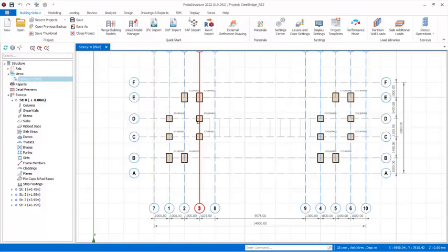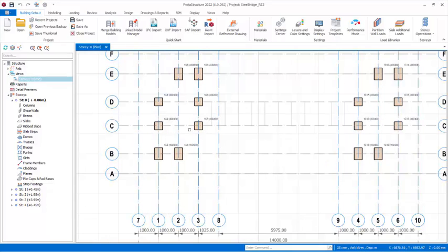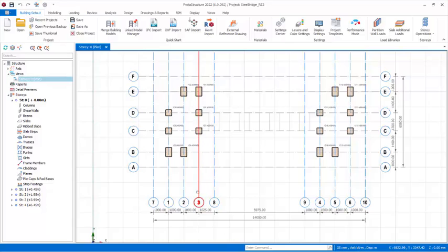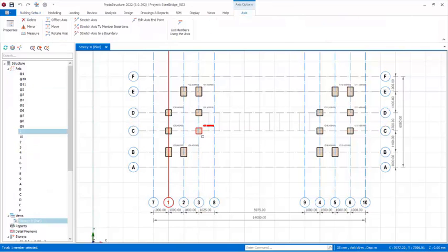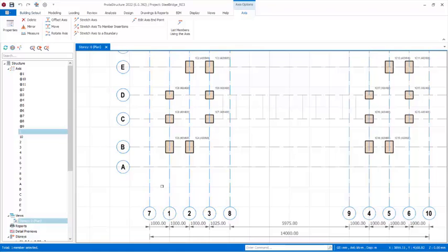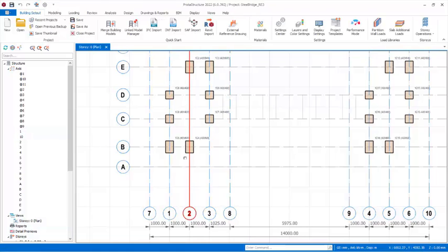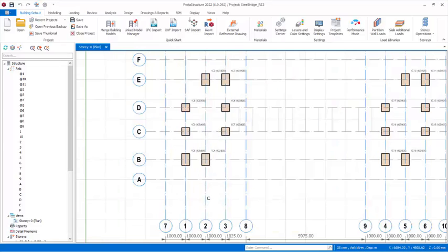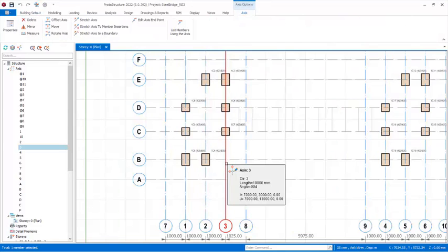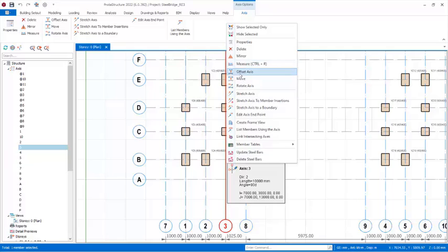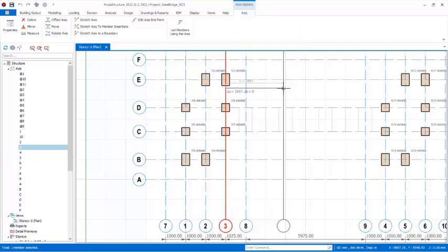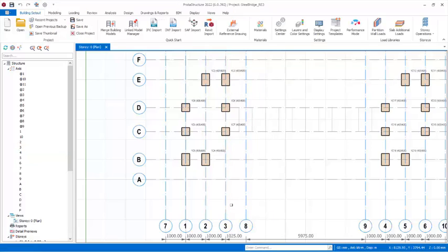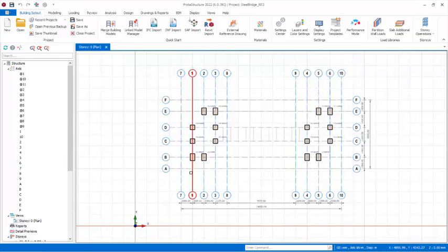So now you can see the setting out line, okay, from grid line 3, grid line 1 right there at the setting out line. So this grid line 7 and 8 is being offsetted due to the foundation design. Now it is being offsetted from grid line 3. Right click and click on the offset right there, hold the shift F2 right there, and then key in the distance. That is how this grid line 8 and 7 we are obtained successfully.